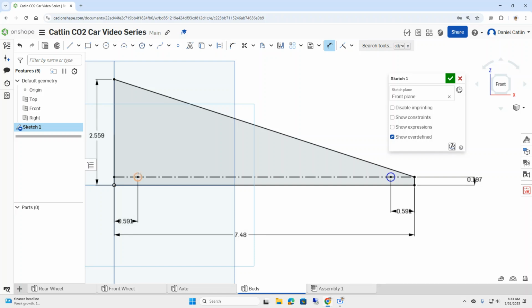The other thing is, let's set the dimensions on the actual diameter of this circle. For this hole, we want it to be larger than the axle's width, which is 125 thousandths of an inch. But what I found to be pretty good, and has nice low friction and gives you a little bit of leeway on size, is 4 millimeters. So if you make the diameter of these axle holes 4 millimeters, with the metal axles that I'm providing, that's 157 thousandths of an inch.